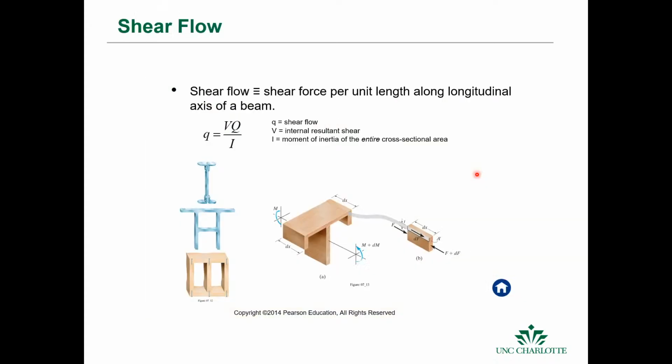Another thing that's related to the shear is the shear flow, and that's the shear force per unit length along a longitudinal axis of a beam. Okay, so that's this shear that's present, that would be in this axis here on this face.